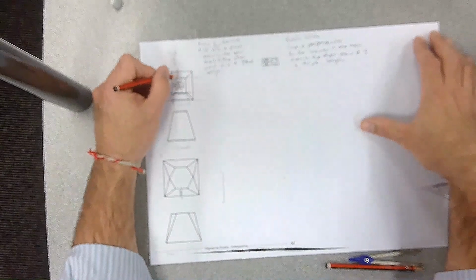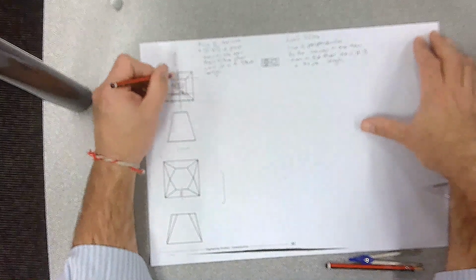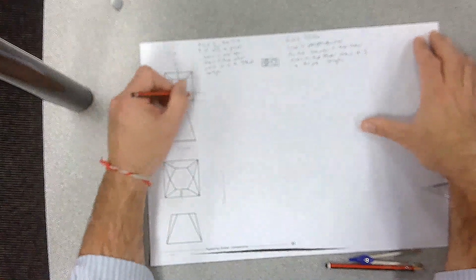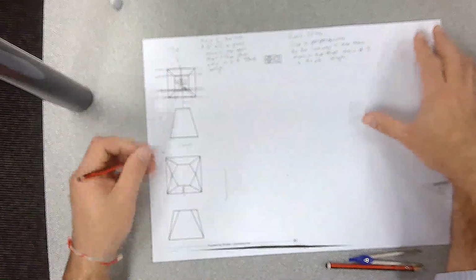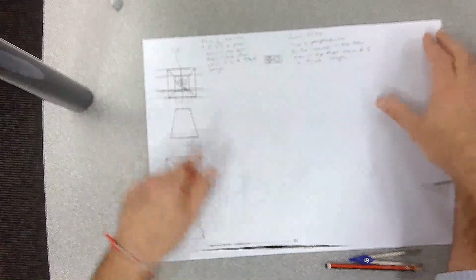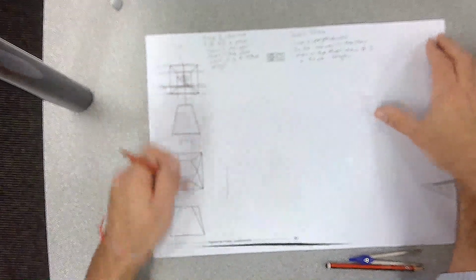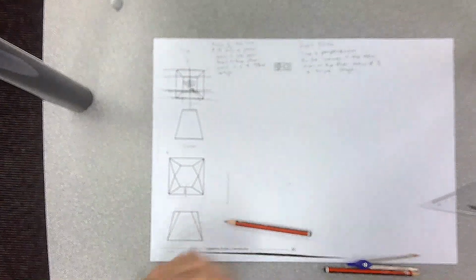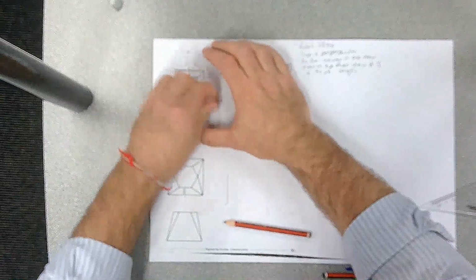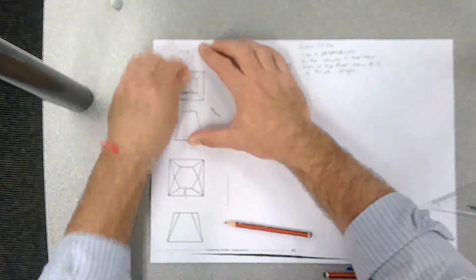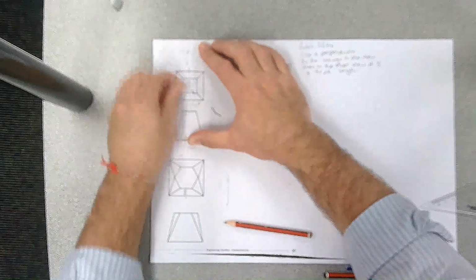So you take a line of symmetry through the viewer, and if your line is perpendicular to the viewer, which is these lines here, then you know that in this view they're going to be true, and vice versa. If it's perpendicular in this view here, then it's true length up here. Okay, now if you remember those rules, you should never ever be wondering whether a line is true or whether it's not a true length.